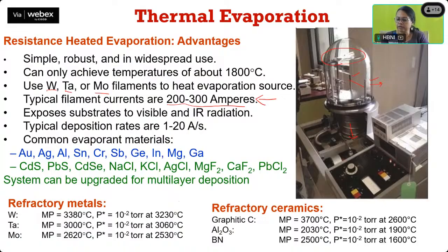monitor inside this. So there will be a thickness monitor, that is generally a C-cut quartz crystal, and it vibrates with some given frequency, and depending on the mass which is getting deposited there, it will give you a value of the thickness of the film which is getting deposited, and depending on that we can change the current which is passing. So that's how we can also regulate the growth rate or the deposition rate.